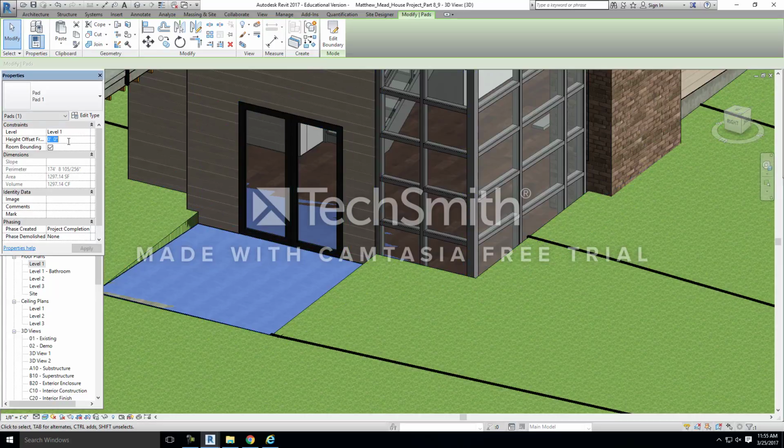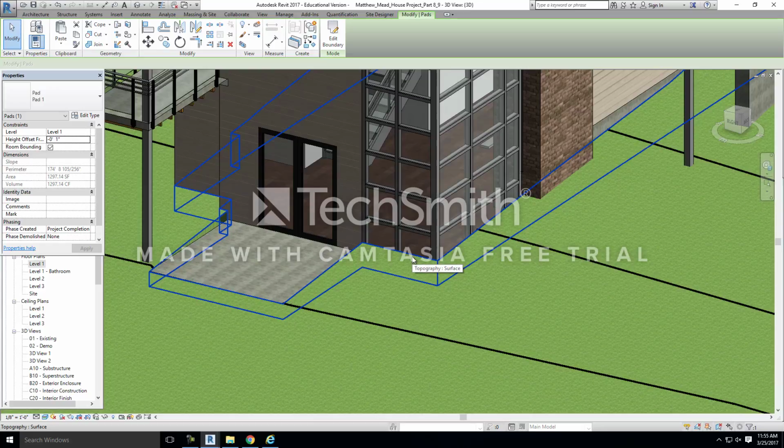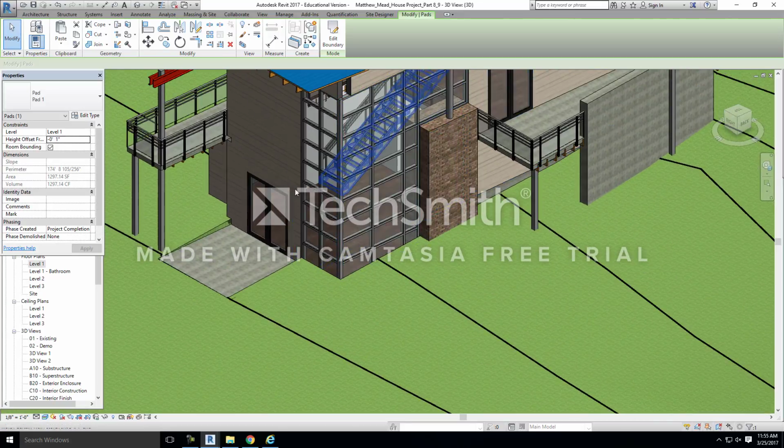You can move the pad down. We'll say, if you just move it down an inch, it will fix that problem of the overlapping. And you could select your floor and make your floor whatever the thickness of just the material is, and that material could sit right on top of the slab. So up to you and how you want to handle that. But if you notice the slab clashing with your floor, the quick fix is just to lower it 1 inch,